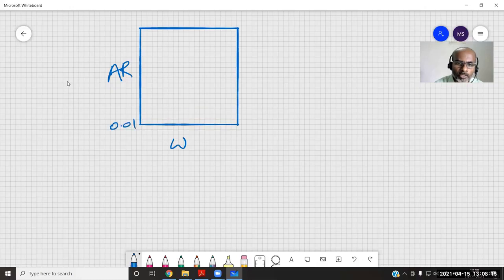So that means we'll be having 0.01, 0.1, 1, 10, logarithmic values for the amplitude ratio. Likewise, for omega also we have logarithmic coordinates, 0.1, 1, 10, 100 like this. We can easily plot AR and omega by simply having the low frequency and high frequency asymptotic values.